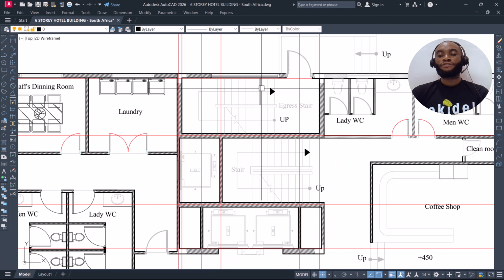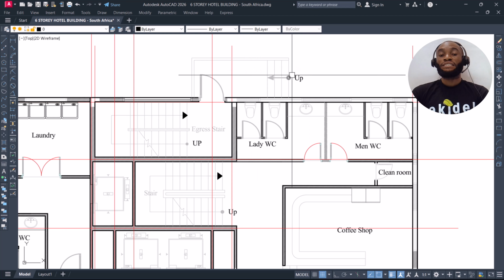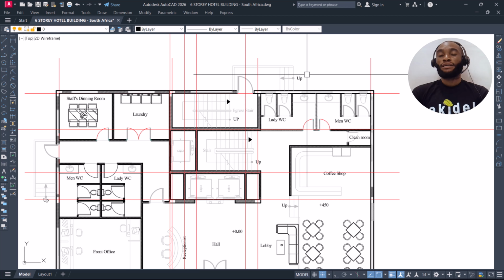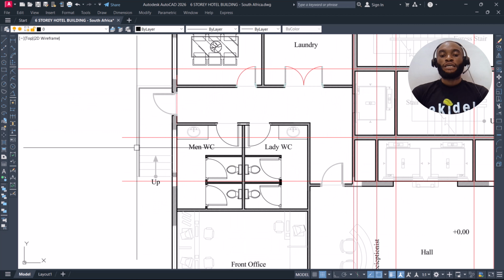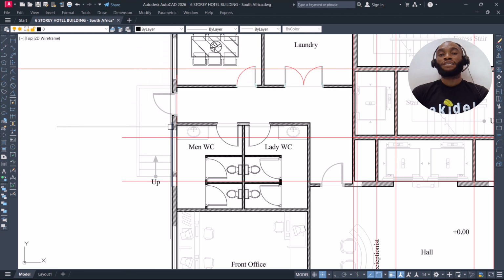Then we have a staircase around this place, and also we have other steps. These are not staircases, but these are steps. So we are not going to design them structurally. This also is a step, but it can be designed structurally. This should just be mass concrete, maybe with a wire mesh, a mesh reinforcement.